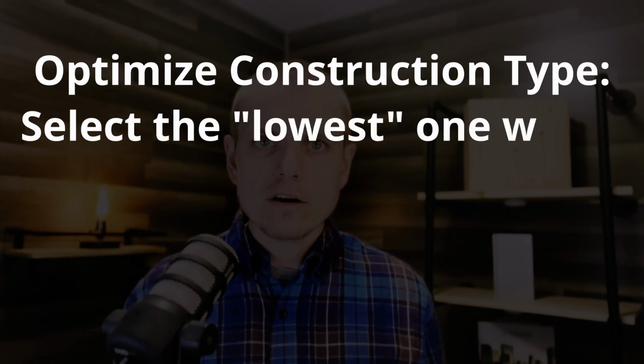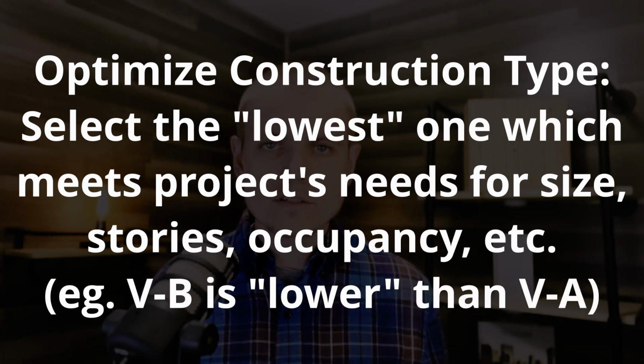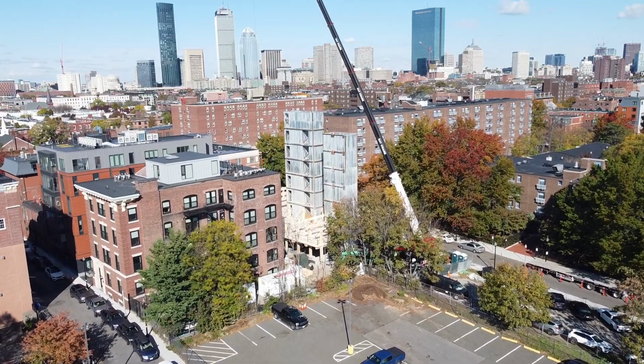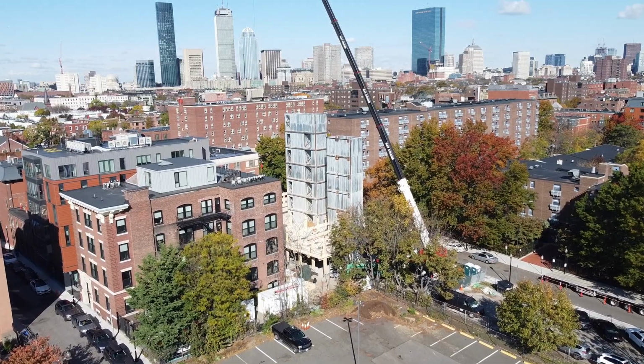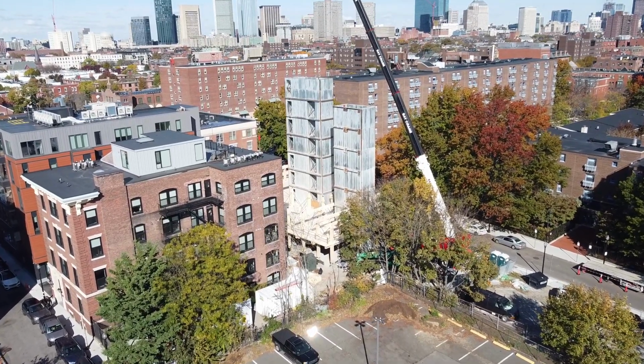Now, starting out by taking a look at what volume of timber does your project need. Now, I harp on this all the time in these videos, and I'm going to do it again today. And I'm going to start by looking at construction type, really optimizing the particular project that you're working on for the best construction type according to the International Building Code. The reason that this is so important is because if you can dial into a specific construction type that has maybe a lesser fire resistance rating requirement than other construction types while still meeting the requirements of the International Building Code for the occupancy and size of the project that you're working on, those lesser fire resistance rating requirements are going to inherently require smaller sized timber members in most cases. Obviously, smaller sized timber members are going to reduce the overall volume of timber needed on a project.